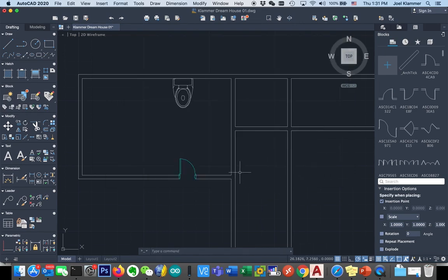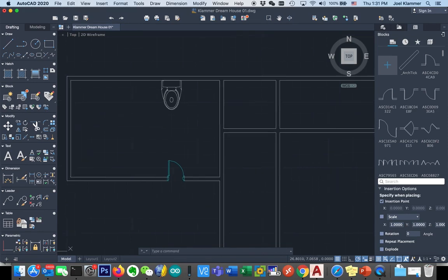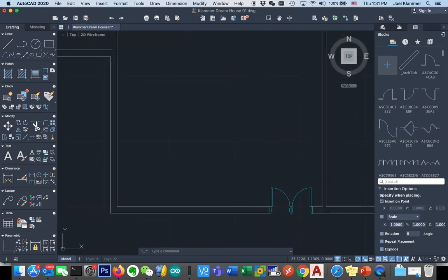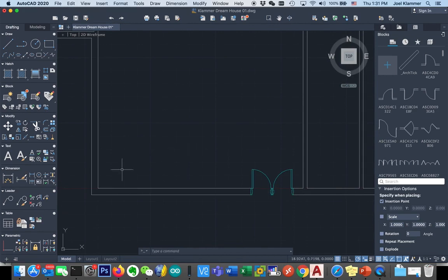How do you do a window? I would just recommend adding little rectangles where you want your windows at this point. So in my master or my main area here, I'm going to want to put a window around here. So I'm going to go ahead and do my old rectangle command. And I'm going to move myself over this way about 2 meters. And then I'm going to draw my rectangle right into here. So a fairly large window. I don't think I actually want it over that far, but my endpoint's going to be there. And so there's my rectangle.